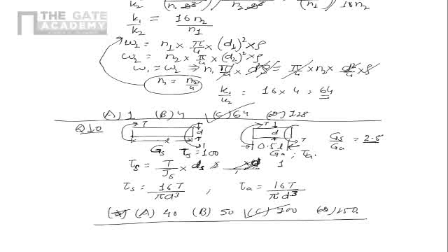So these are all the questions for the chapter on torsion which have appeared in GATE Mechanical Engineering, and I hope you have got a clear understanding of what kind of questions come. Normally the questions are easy. Most of them will be either step shafts or parallel shafts and spring questions, and because we are dealing with only circular shafts, please remember the formula of maximum shear stress, which is 16 T upon pi d cube, and that will be the most important relationship actually.